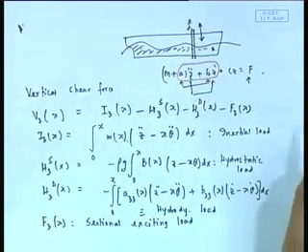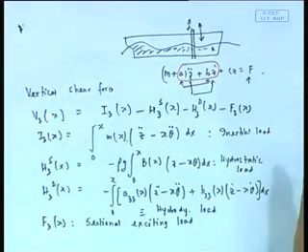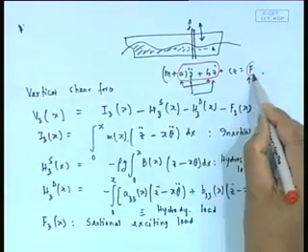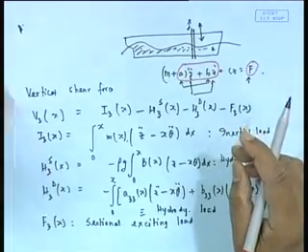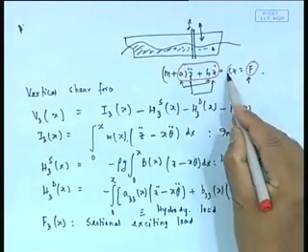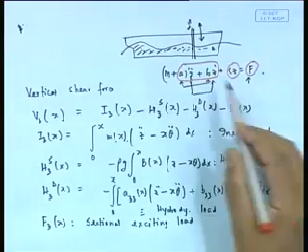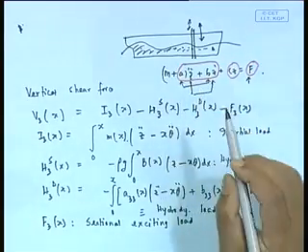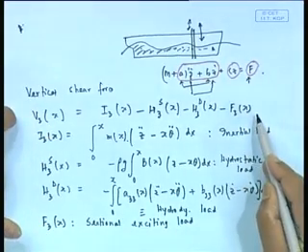This is basically the added mass and damping load arising because of a certain pressure field created. This was an exciting load arising because of again a certain pressure field created by the wave structure interaction. This was the load arising because of the hydrostatic restoring force. And then of course, mass into acceleration would be the so-called inertial force. So all this can be taken.